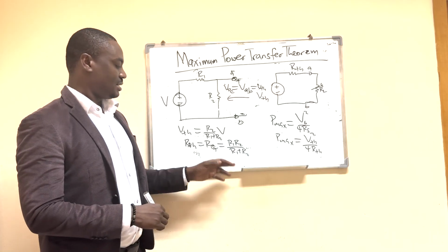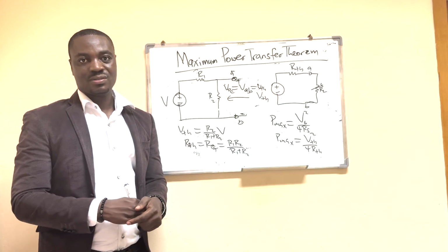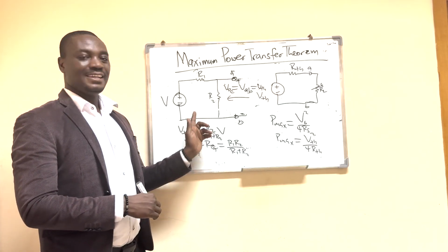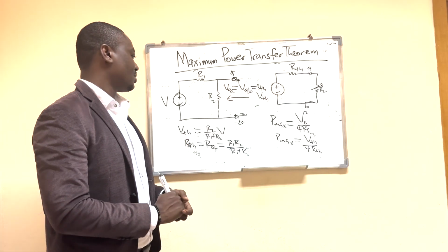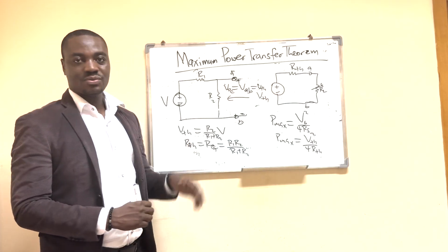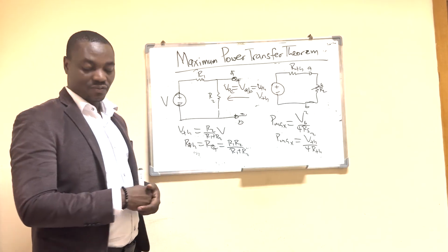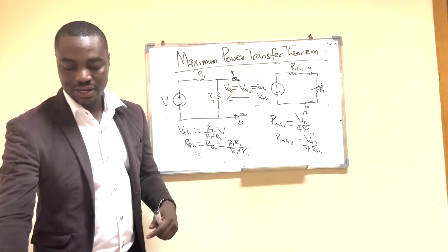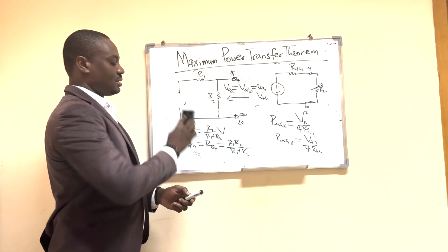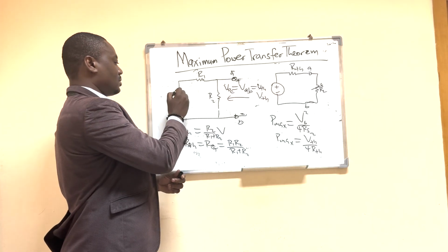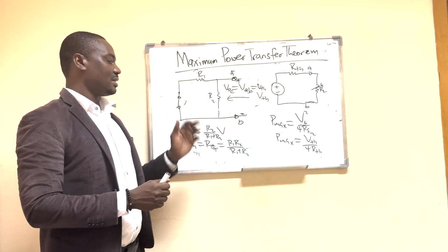And we can obtain it by making sure that all independent sources in this linear active circuit are turned off, meaning we make all of them zero. So say I have a voltage source. When it comes to a voltage source, you make the voltage zero by short circuiting it. What this simply means is that I'll take a wire and connect it to this. So we indicate it this way. This means I'll short circuit the voltage, and that voltage here is zero.